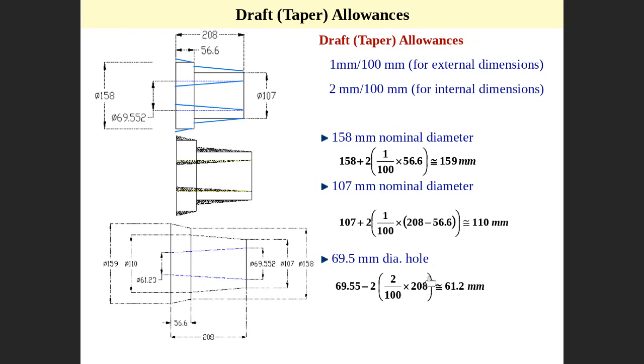Then every dimension will have this draft allowance added. This is actually very simple. Let me tell you, this is done automatically by the computer in software. As I told you before, we have what we call Magma software. This Magma software is used in casting. You make the drawing of the part you would like to have, put it in the Magma software, and then the Magma software adds all the dimensions based on what we described here. Then finally you get the final dimension.